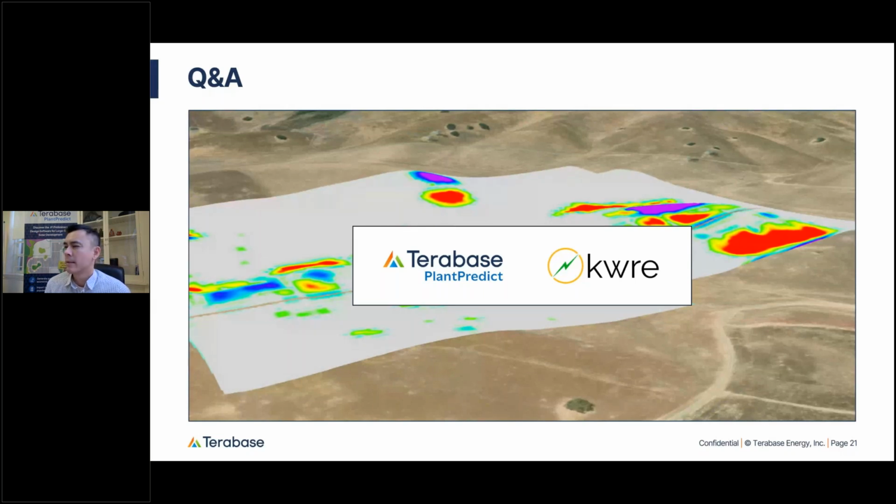And I could be wrong on this because I'm not a PVCase expert, but they're not providing nested blocks as piles within tracker blocks. But if they are, you can do that. Or if you could update the tracker blocks to have a nested block as a pile rather than how the PVCase data structure is, then it would be compatible.